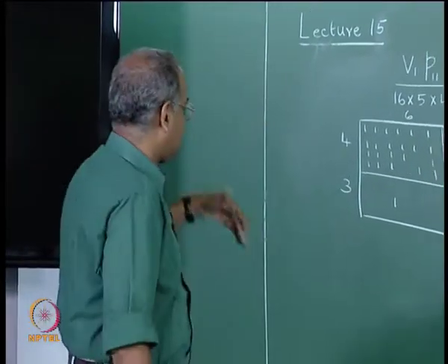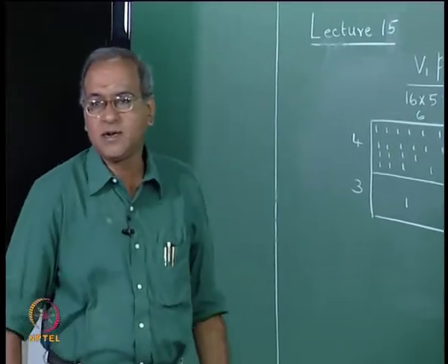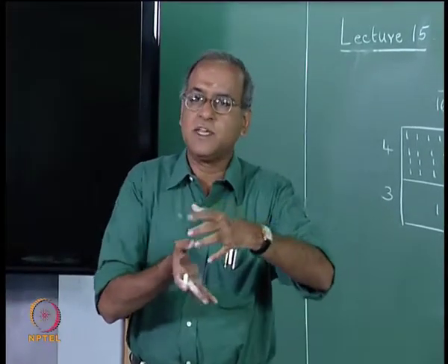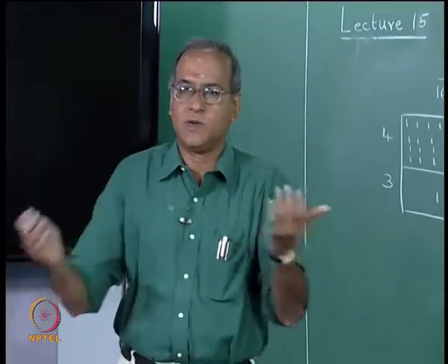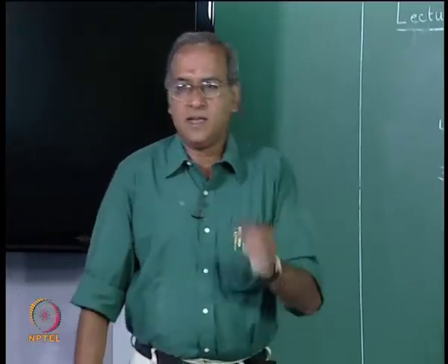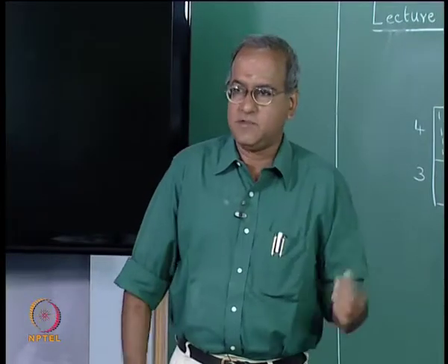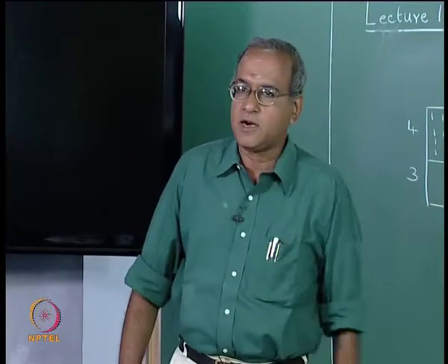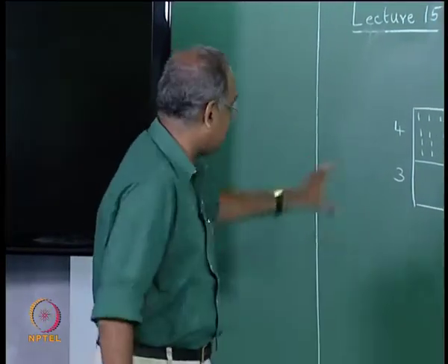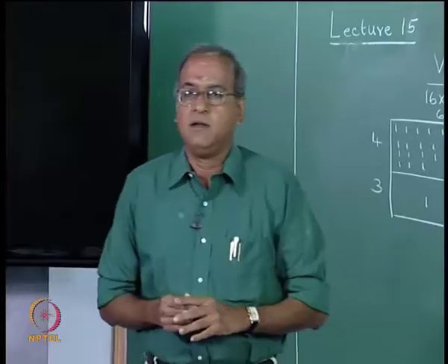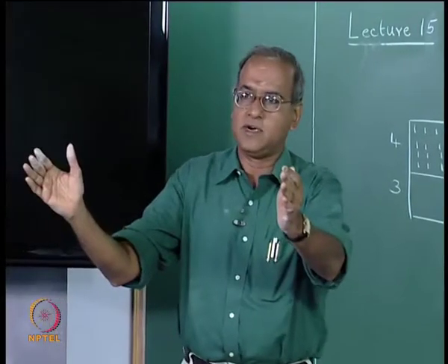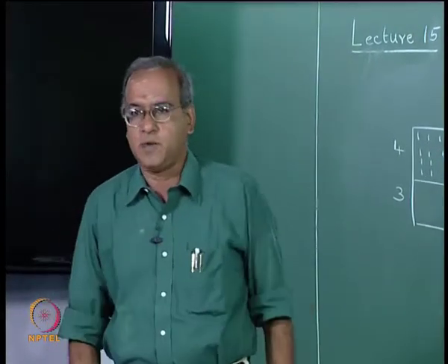When we actually work it out on larger problems, we will not have cells of equal size or part families of equal size. In fact, the larger instance that we have seen, the 16 machine 43 part problem, gave us something like this, where there were 5 groups. Some of them had more machines, some had fewer machines, some handled a large number of parts, and some handled fewer parts.